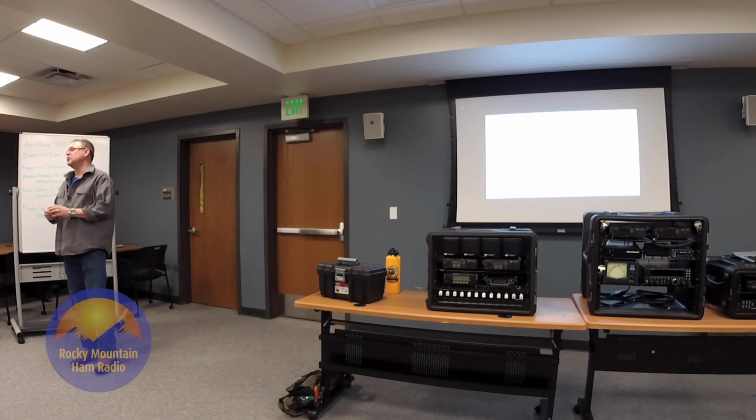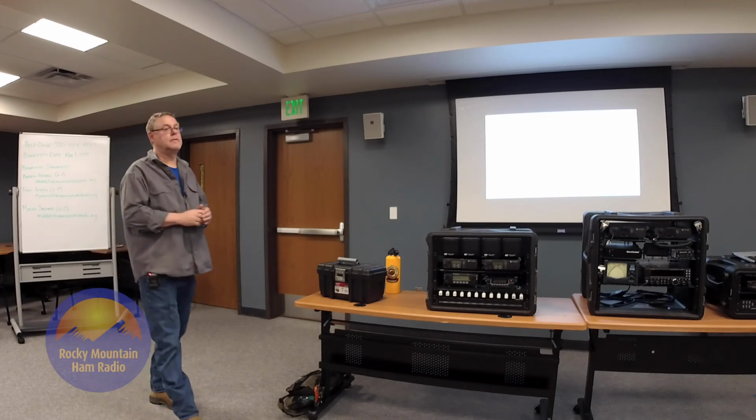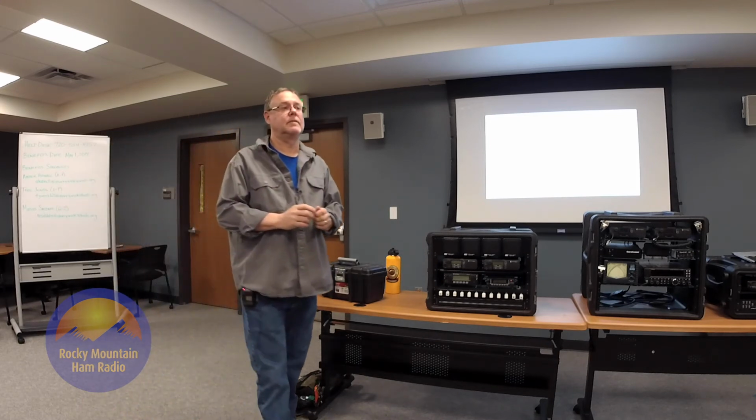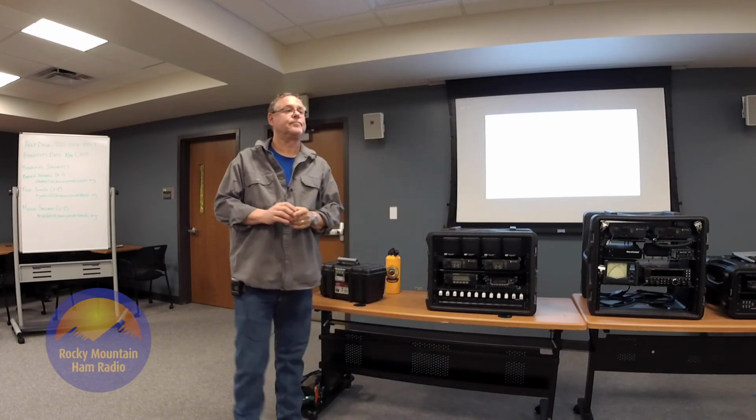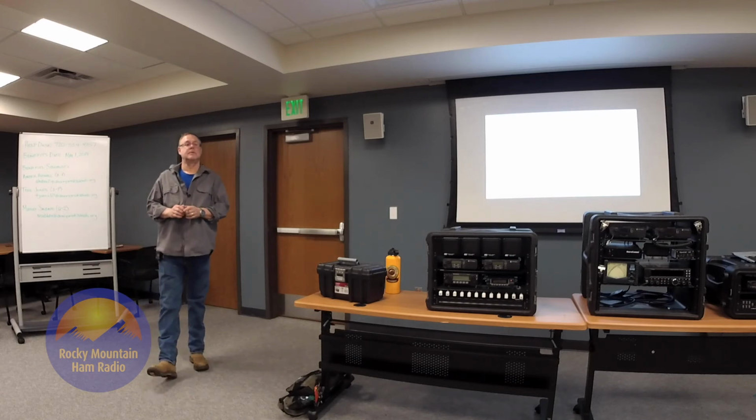But you need to put it as close to the output of your generator as possible. Yeah, with the generator, it's a little hard to get in there, so I just put it straight at the outlet. It also helps, in that case, to go find yourself a big donut toroid and wrap a couple of wraps of your extension cord really close to the generator through it. That will stop a lot of the radiated noise down that long antenna you have laying on the ground.